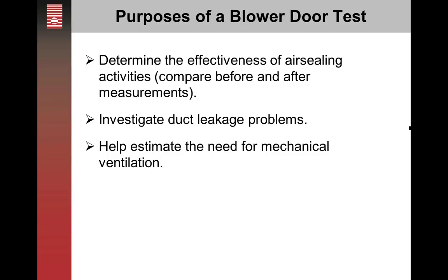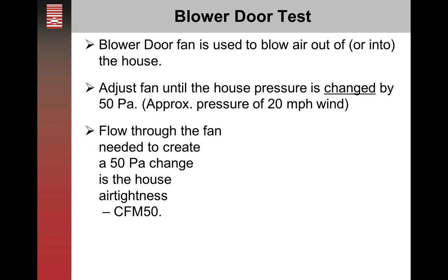We try and seal up these houses as tight as we possibly can, but then we also need to figure out, how do we bring fresh air into the house? Through a blower door test and determining the air tightness of the structure, that will help us in determining mechanical ventilation requirements for makeup air.